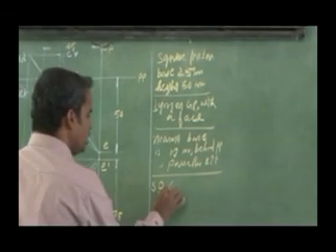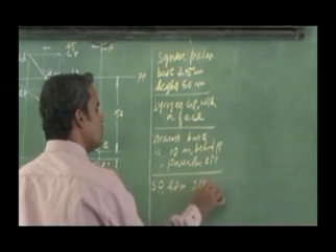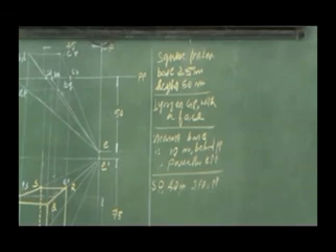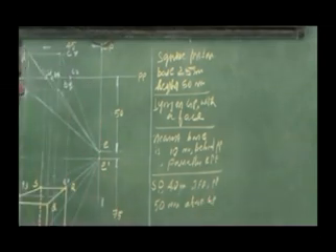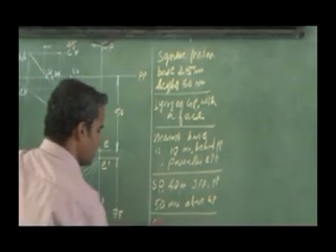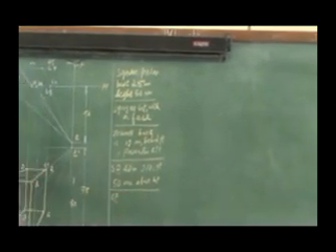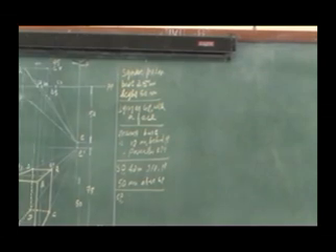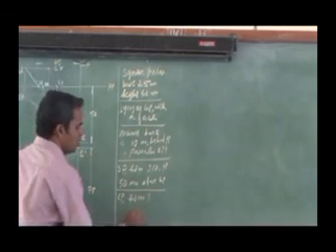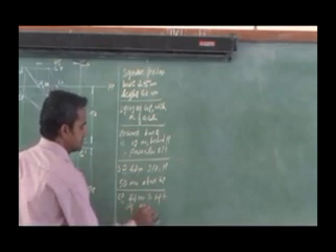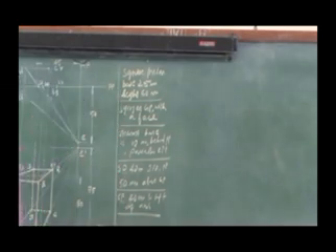The station point is 40 mm in front of the picture plane, 50 mm above the ground plane, and lies on the center plane, which is 40 mm to the left of the axis. Draw the perspective view of the prism.